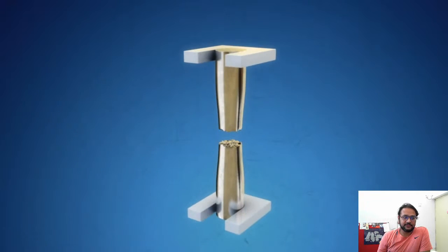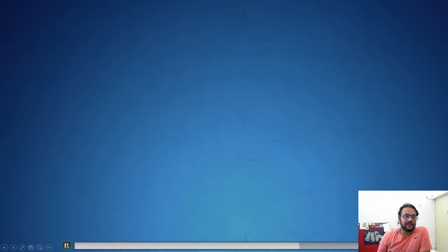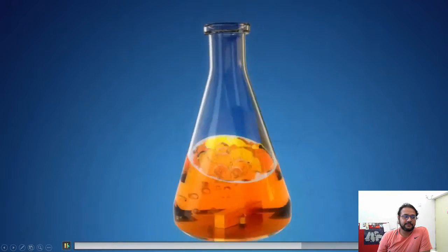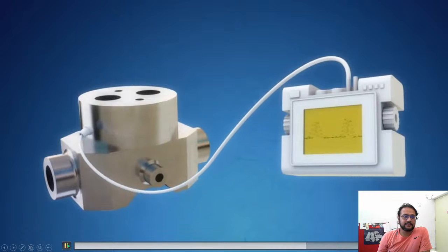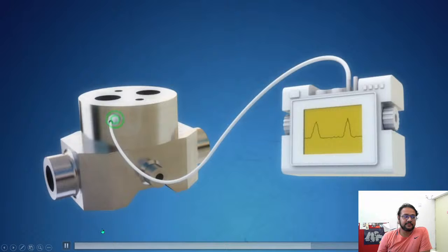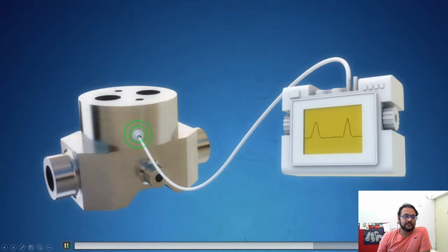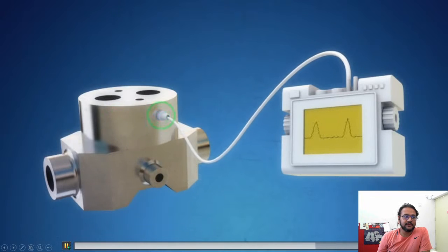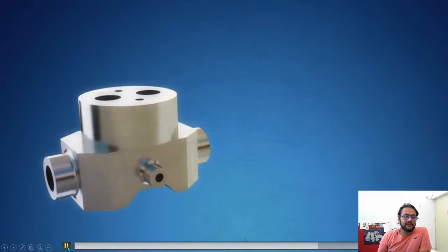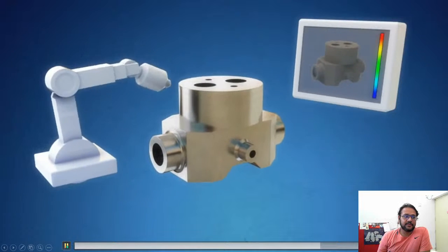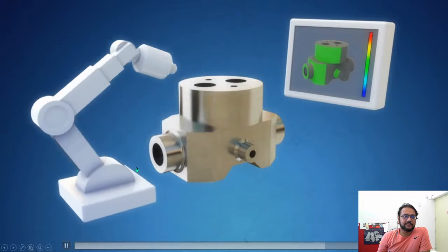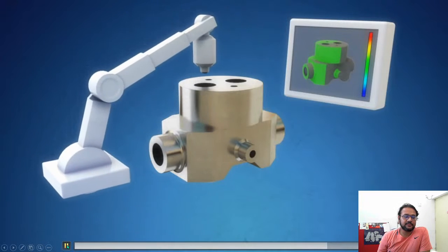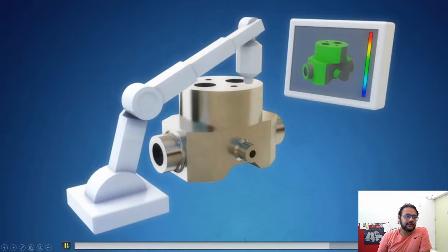The HIPed material undergoes destructive testing to verify strength, toughness, corrosion, and structural properties. The final product is fully inspected for defects using non-destructive ultrasonic and dye-penetrant testing methods, as well as ferritoscope and positive material identification. The geometry is evaluated by laser scanning after the HIP process and before machining to verify that the product meets specifications.